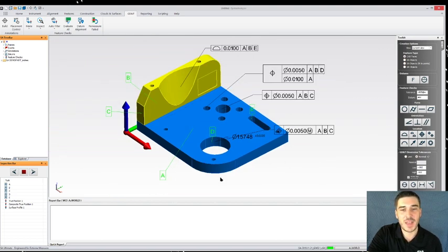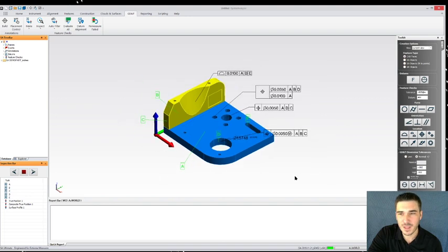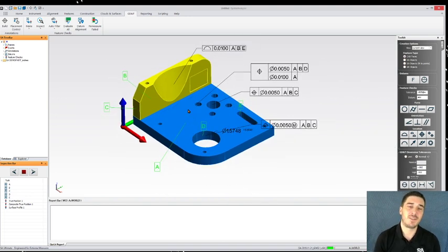And the great thing about that is, as you go through and inspect this, this gets a bonus tolerance for being inside its tolerance for its feature of size, and SA will automatically calculate that bonus tolerance for you. It's not something you have to add manually or anything like that. So that's the real basics of how to set up a GD&T inspection if you don't have model-based definition, if it doesn't come in automatically with the model.